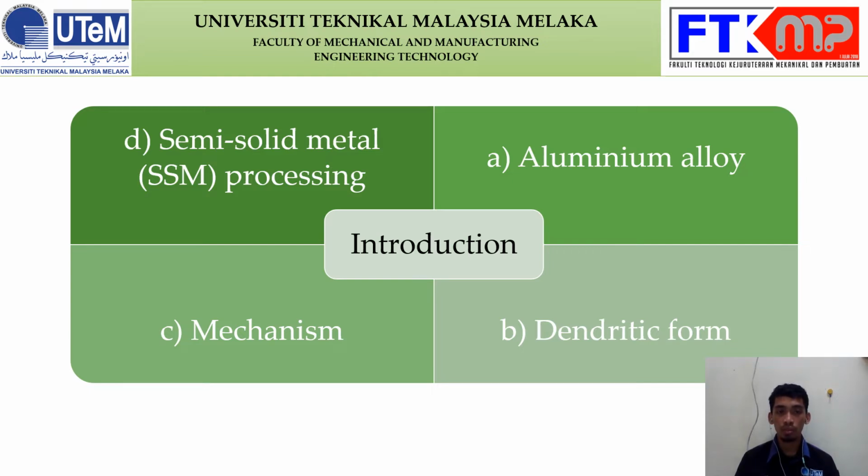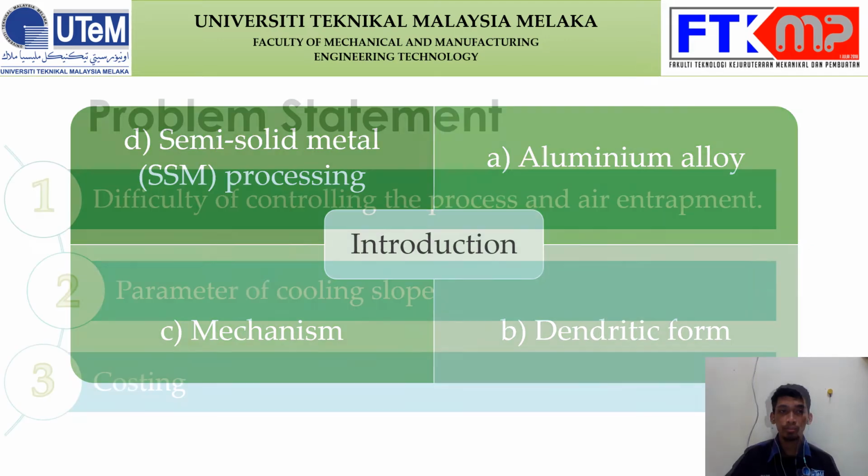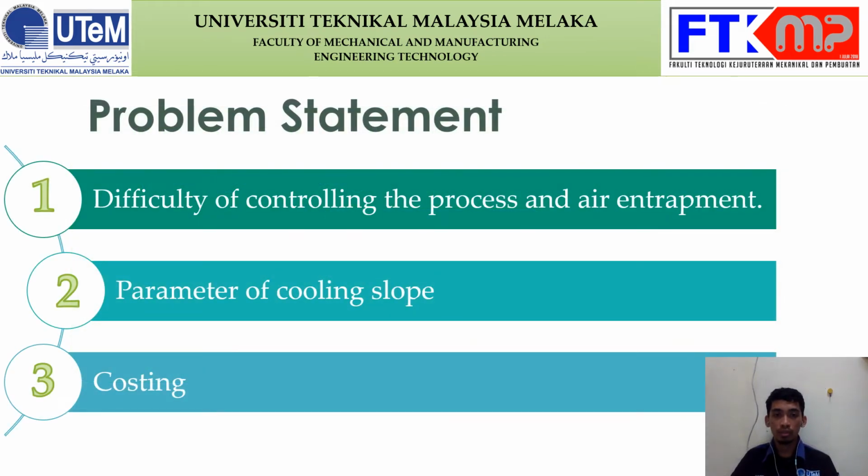Semi-solid metal processing can be separated into two categories, either from the liquid or the solid state. After doing my literature review, what I found is that the cooling slope is one of the mechanisms to change the grain microstructure from dendritic into non-dendritic form.